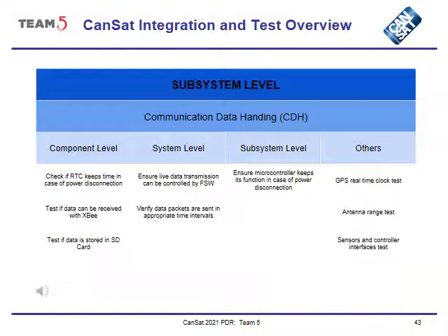For communication data handling CDH, we have in the component level, check if RTC keeps time in case power disconnection, test if data can be received with XB, test if data is stored in SD card. For the system level, ensure live data transmission can be controlled by FSW, verify data packets are sent in appropriate time intervals. And for subsystem level, we have ensure microcontroller keeps its function in case of power disconnection. Others, GPS real-time clock test, antenna range test, and sensors and controller interfaces test.